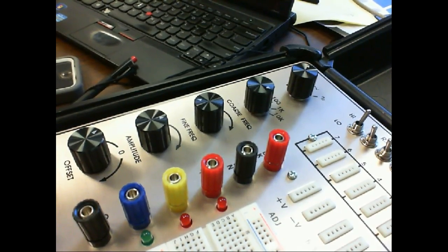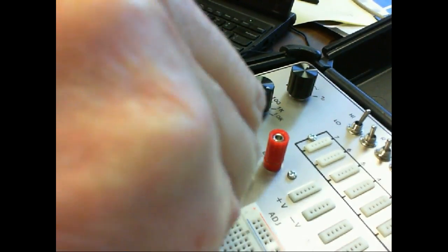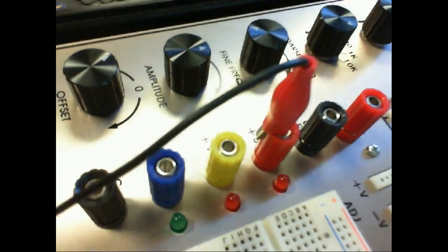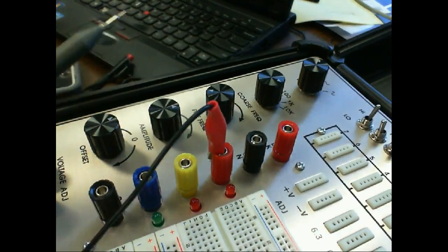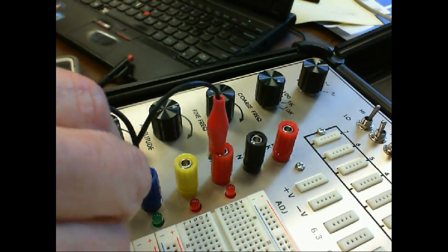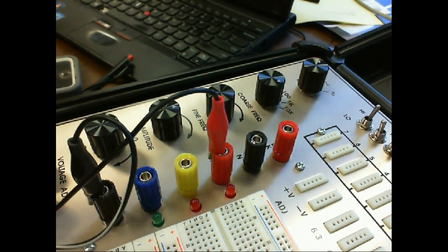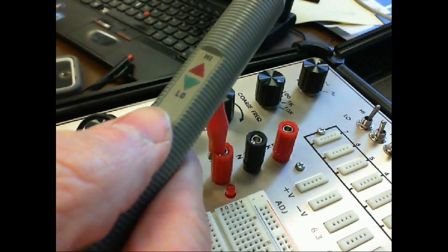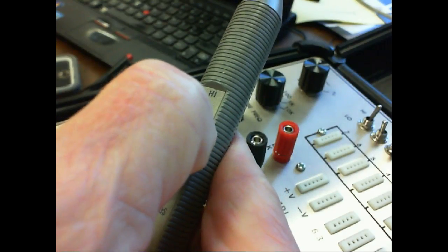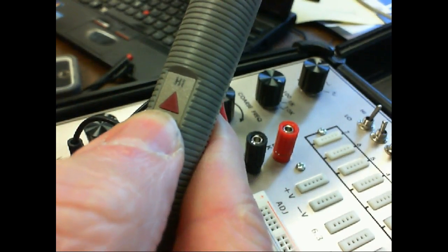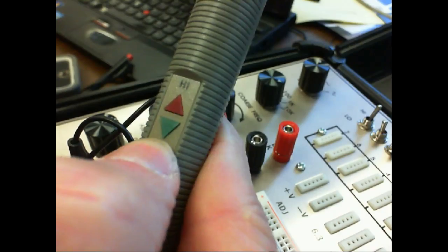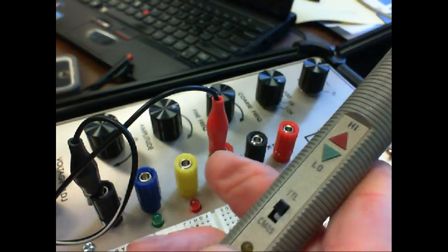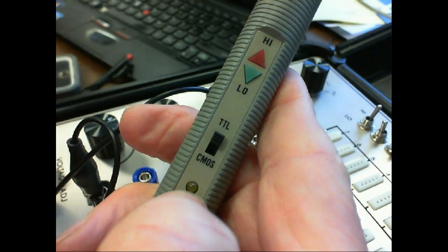So that means what we need to do to power this thing up is, we have to hook this up to the plus 5 volt supply. Y'all can't see it. So here's plus 5 volts. And then this right here would be ground. And then we need to turn this to what? Right now we're going to turn it to TTL. This red light comes on when it sees a what? High. The green light comes on when it sees a low. And this light right here comes on. It's not labeled. It comes on when it sees a pulse.